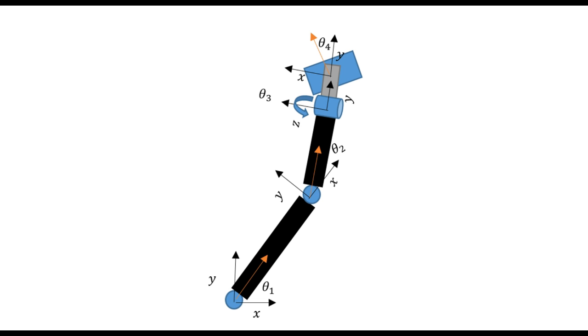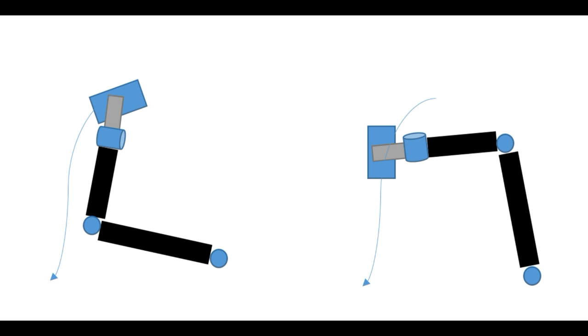Furthermore, the Denavit-Hartenberg convention for the angular position and the joint reference frame was used for motion. You can see here the angles and reference frames. θ1 refers to the angular displacement from the fixed reference frame to the rotated reference frame due to the rotation of joint 1. θ2 is homologous to θ1 but for joint 2.